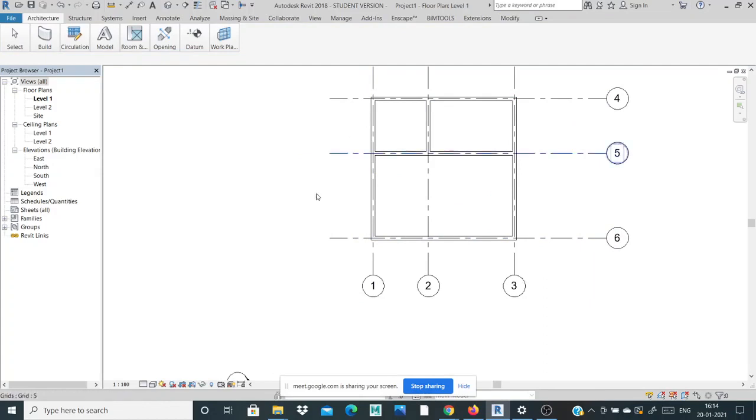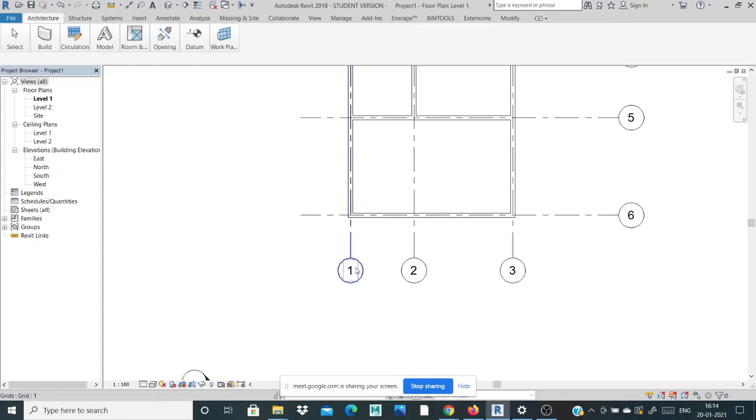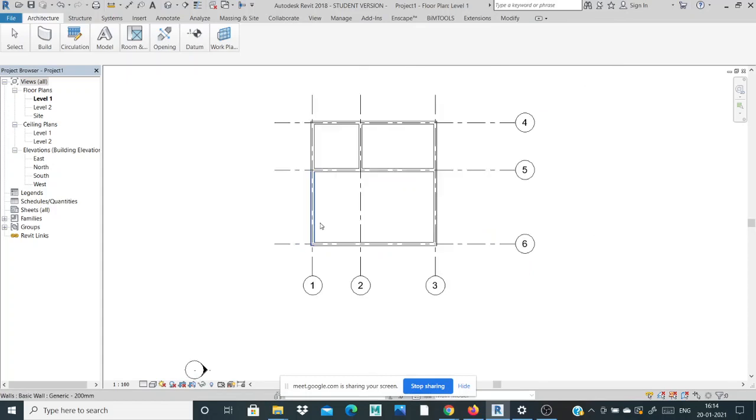There are some rules. You create the grid lines 1 2 3, and the opposite direction a b c. The purpose for which they are created, I will tell you after. Sometimes you create 1 2 3 in this direction and provide a b c in the other, right? How to create the a b c? Simply double click this box, right? Click a on your keypad. Double click B, then C, right? See this, it is automatically created. One is A1 already in this diagram, right?